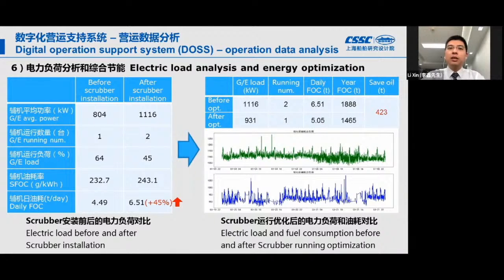It is not to say the main engine is running at 100% capacity all the time, so the scrubber systems can lock up the rotating speed of the main engine in order to reduce energy consumption. If the main engine is not at 100% capacity, then the running of the scrubbers does not need to run in its full capacity either.